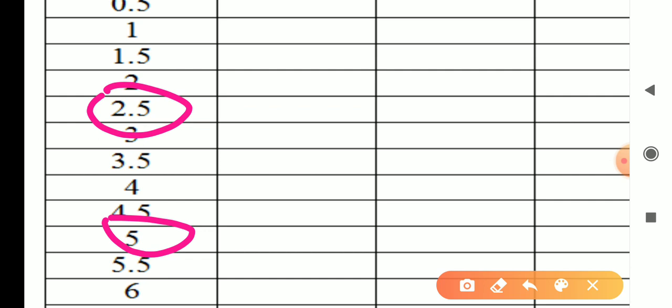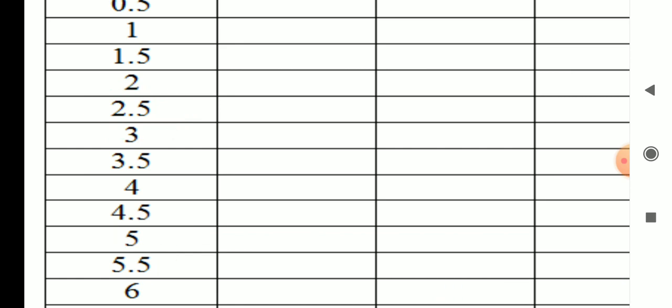If you press any material, say a sponge, up to some penetration it will take the load, and after that it will not take the load. Once it has crossed the pressure, it will not take any more pressure. That's why we don't want further penetration. Based on trial and error, only 2.5 and 5 penetration are considered to find CBR percentage.